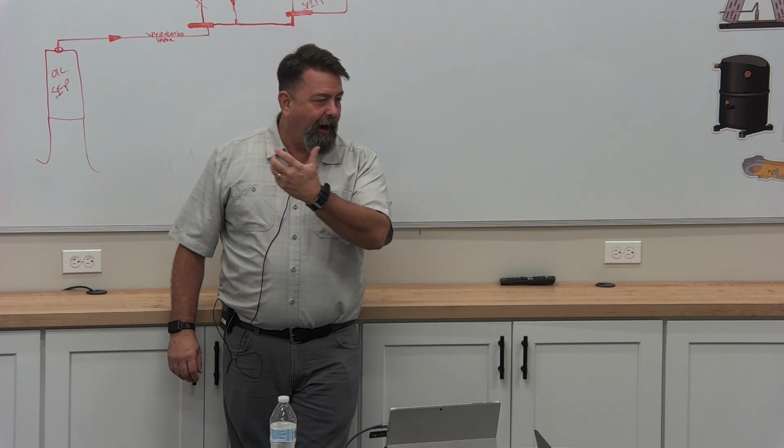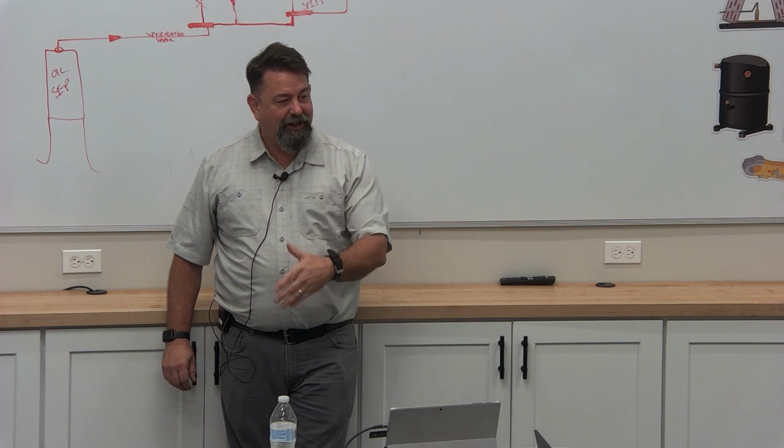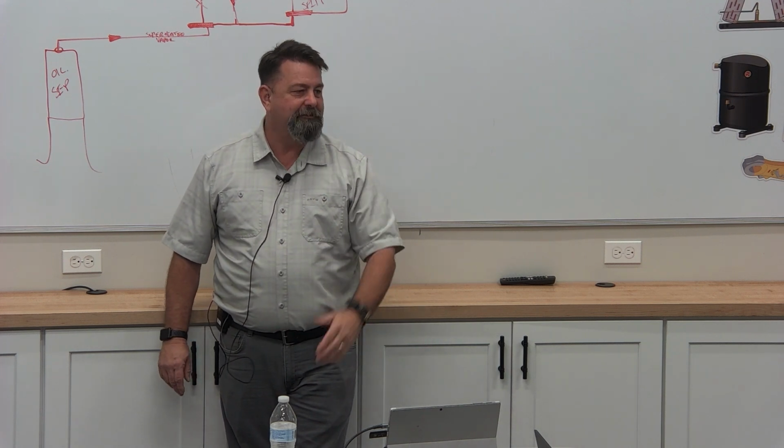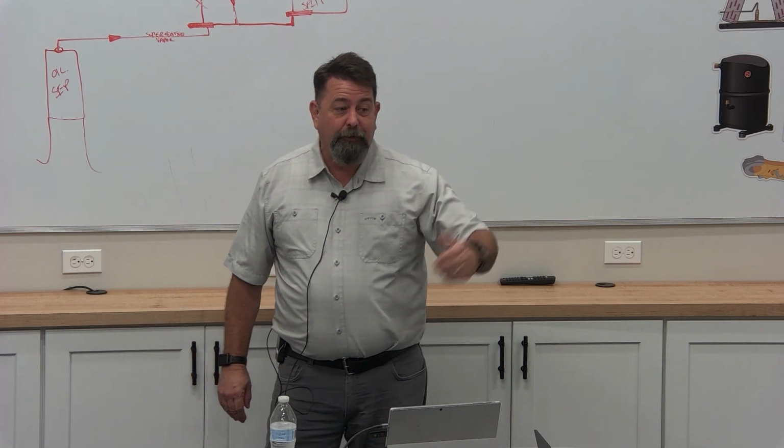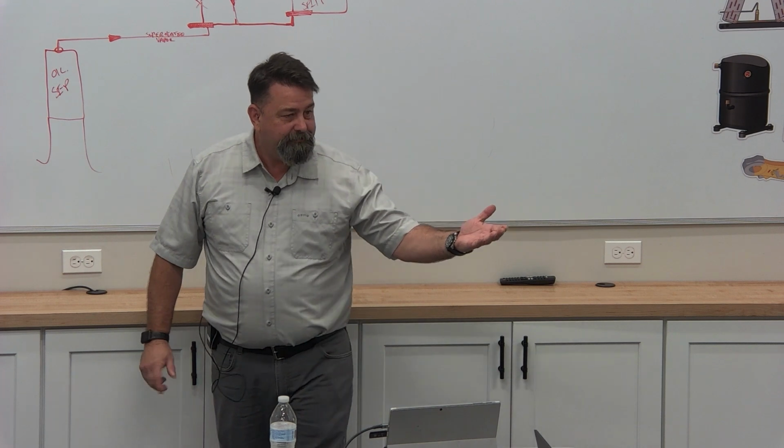These are all self-cooled motors, being cooled by the airflow. The airflow through it is going to cool to match the electrical heat load, and I'm running half. I gotta turn off my mechanical brain or my automotive brain. Mechanically, that motor's just fine. It's just gonna move half as much air as it needs to not overheat, right?